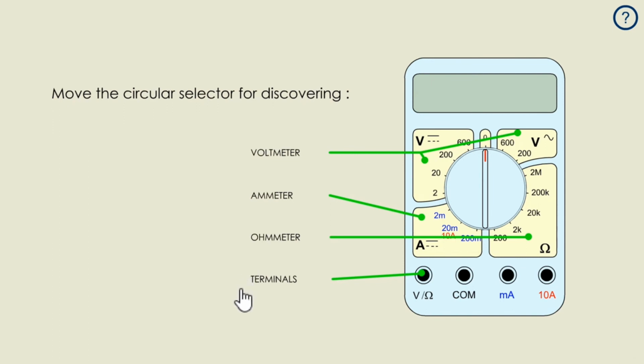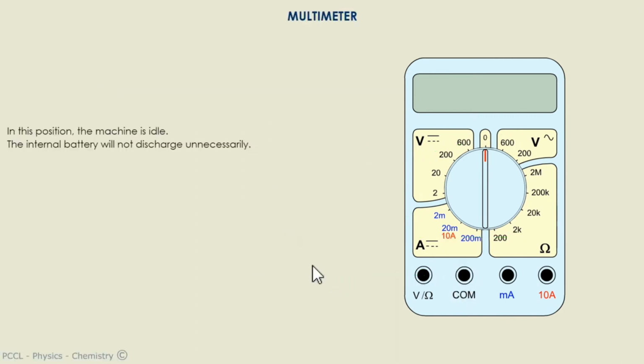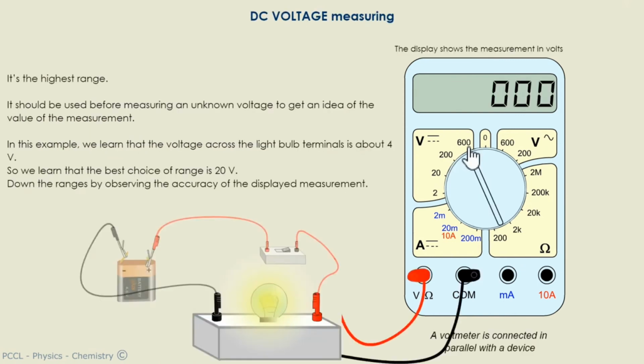It is always used with two connection wires. One of the two wires is always placed on the COM terminal because it is the common terminal. The question will arise for the other connection wire. If we want to measure voltages, then there is a wire on the COM terminal. It always will be. The other wire will be on the connection terminal noted V, as in volts.